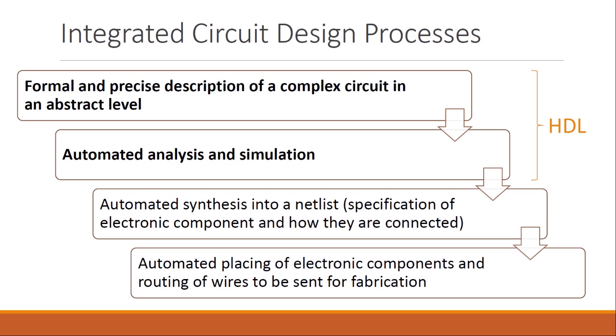So you first describe the circuit in a hardware descriptive language like Verilog, and then you need to convert this into a real circuit. Generating a real circuit out of a model described in HDL is called synthesis. So the automated synthesis into a netlist is the third step of the design procedure of integrated circuits. The netlist is the specification of electronic components and how they are connected.